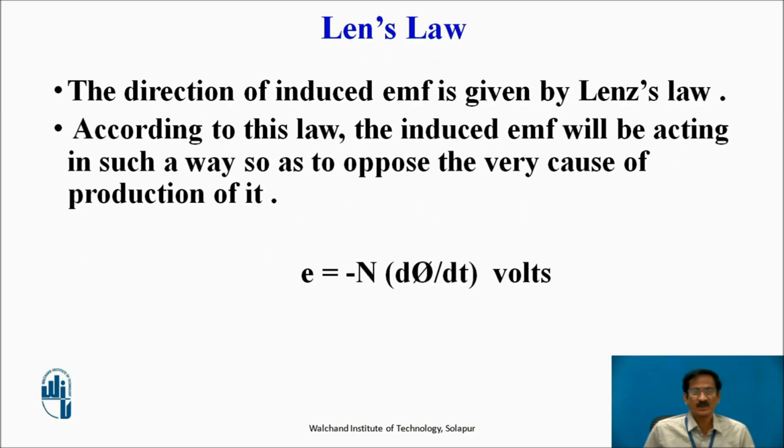Lenz's law. The direction of induced EMF is given by Lenz's law. According to this law, the induced EMF will act in such a way as to oppose the very cause of its production. Mathematically, we can express Faraday's law of electromagnetic induction and Lenz's law as E = -N dφ/dt.